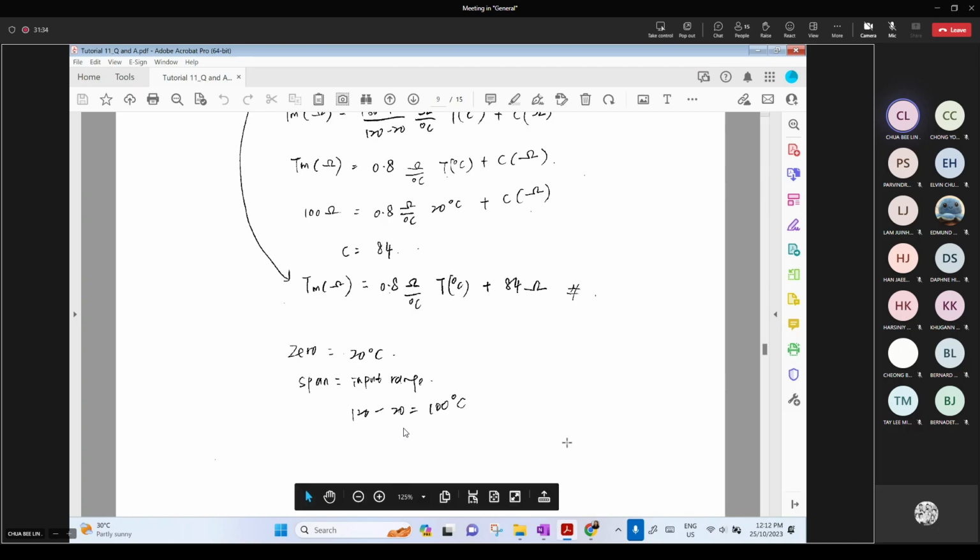Okay, and then the second order dynamic behavior. It's just a revision scope. So please make sure you go through the second order dynamic behavior, very similar to the test question. Make sure you convert the last term into 1, and then you calculate the overshoot, damping factor, time constant. The solution also was already posted to MyTimes.